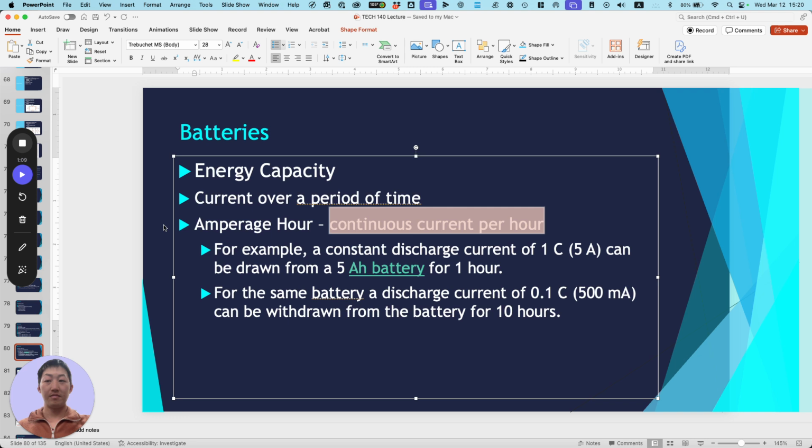So theoretically, you could, although it's a little dangerous because you can see what happens if you mess up with lithium-ion batteries. We have our cells from the battery from last semester. There's like 2 or 3 of them where one cell is dead. The rest are fine. So technically, you can take out that bad cell, take a good one from the other battery, put it in, and restore the battery. And I know on a Prius car, they have the battery, and sometimes it's just one cell that's dead.